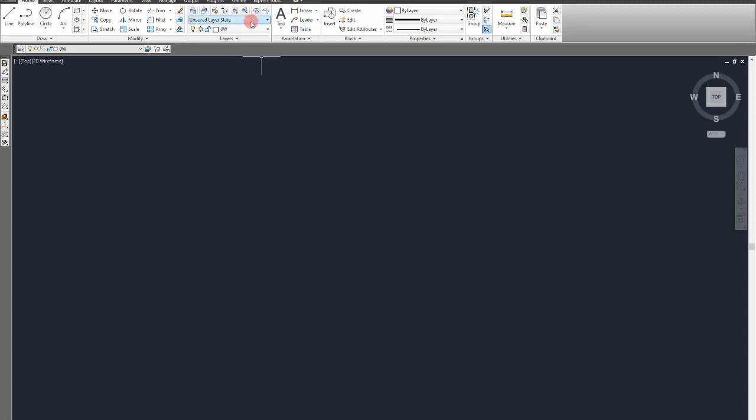We have this toolbar, which is for text. I will mention it. It's also one of the most used commands in 2D drawings. Insert, we use this for blocks. Blocks are basically groups of elements that may have certain attributes and they are unified by their function. Like you have a group of furniture elements, a group of mechanical elements, and you can insert them with one click instead of copying all elements and pasting them. The block is one element. It may contain many sub-elements like many lines, polylines, and so on, but the block is just one. It can greatly simplify the drawing.